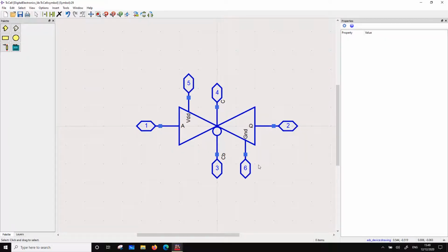In gates, you can never do that, because they are based on pull up and pull down, and you can create a short between VDD and ground for certain inputs. So that's why gate outputs are never connected together as they are. Okay, so this is the difference we should know, that this has an additional state which is a high impedance state. Okay, so let's do that.